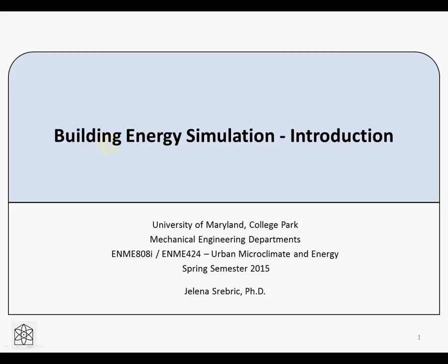Welcome. This series of lectures is an introduction to building energy simulation. We'll go over a brief background of energy simulation and how it is used, learn how to benchmark your building to other buildings with known utility data, learn about some key model parameters and their typical values, introduce sensitivity analysis to see which parameters are most important in your model, and lastly talk about model accuracy and calibration.